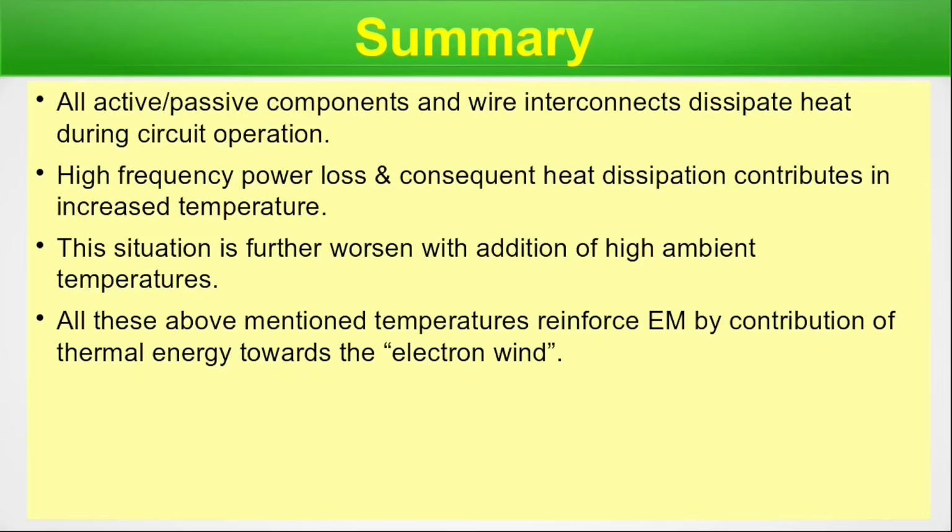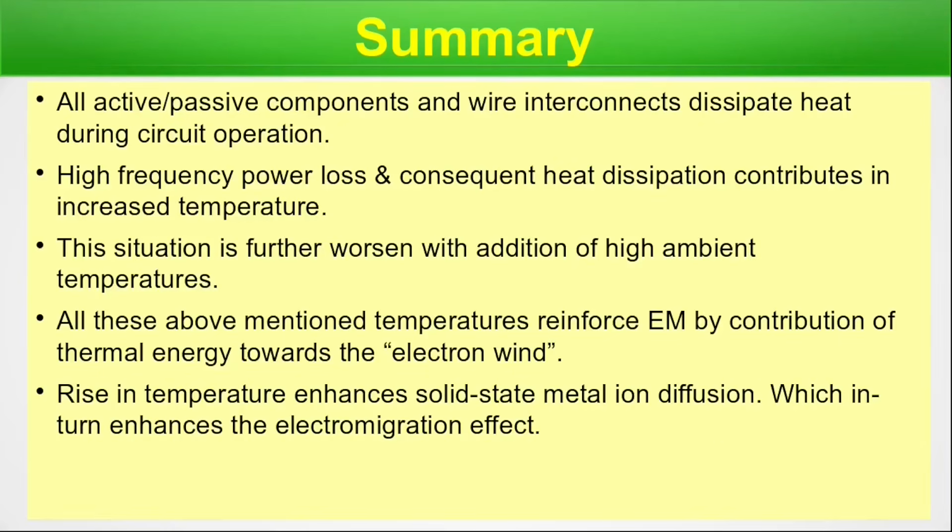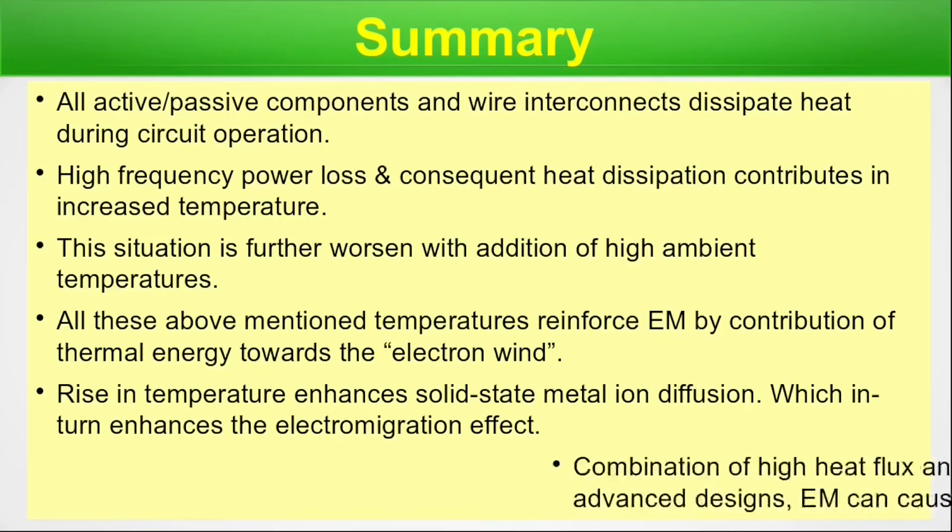All of these above mentioned temperatures reinforce EM by contributing thermal energy towards the electron wind. This is a very important point of this episode, right? All the heating effects we have talked about, all those temperatures reinforce the EM by throwing energy towards the electron wind. Rise in the temperature enhances solid state metal ion diffusion, which in turn enhances the electromigration effect.